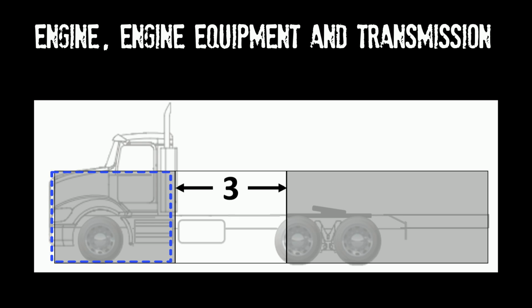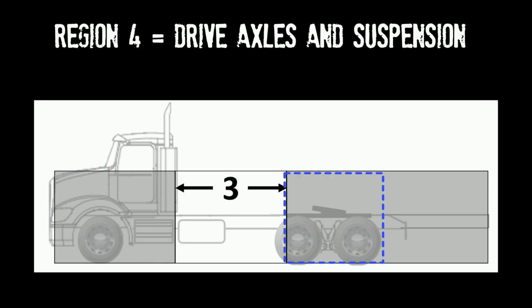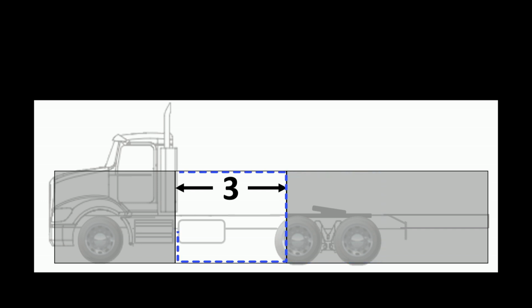Regions 1, 2, and 4 are well defined, limiting opportunities for optional components or special engineering. Region 3, the center frame, offers the most variability, especially with longer wheelbases. This area is covered by drive lines and cross members, leaving the exterior free for customer components.